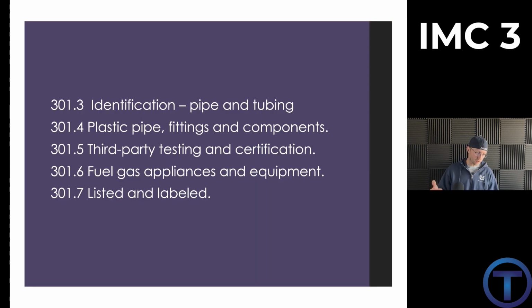Now there's a series here I'm going to just go through quickly. Identification is 301.3. You should have identification on the pipe and tubing. 301.4 talks about plastic pipe fittings and components. Gives certain standards for those. 301.5, third-party testing and certification. Similarly, the things that we install for mechanical systems should be third-party tested to make sure that we're providing higher quality stuff. They meet standards, right? 301.6, fuel gas appliances and equipment. Again, they have to meet certain approvals. And this section refers us over to the International Fuel Gas Code, saying, like, we're going to install mechanical systems, but this is very much in parallel with the International Fuel Gas Code, which has specific regulations on the gas side, the flue side, the appliance side, right? And 301.7, all these things we install have to be listed and labeled.